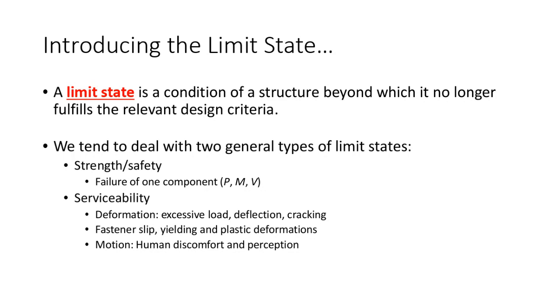However, there's a whole assortment of other types of limit states that we have to design for. One of them is just deflection. If a beam deflects too much and it deflects elastically, in no way, shape, or form does that mean it's going to fail and fall down and kill somebody, right? A beam can deflect a fair amount and still not fail, but that doesn't mean we want that to happen, right?